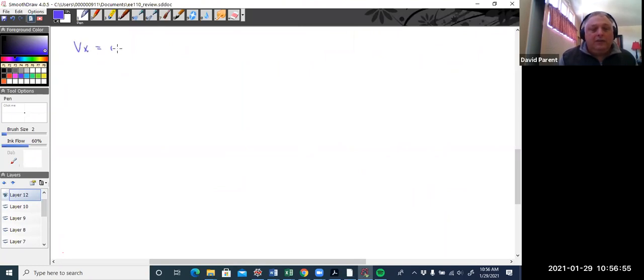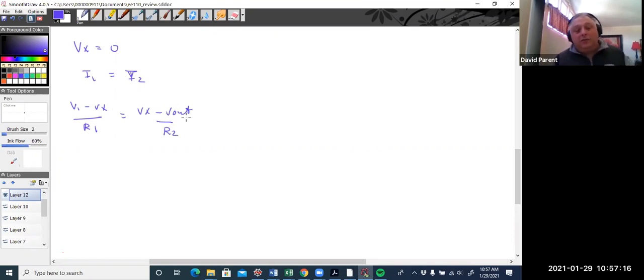So we just showed that Vx is 0. Well, then we go back to our original equation, right? I1 equals I2, which was V1 minus Vx over R1 equals Vx minus V out over R2. And we didn't know which was which, right?